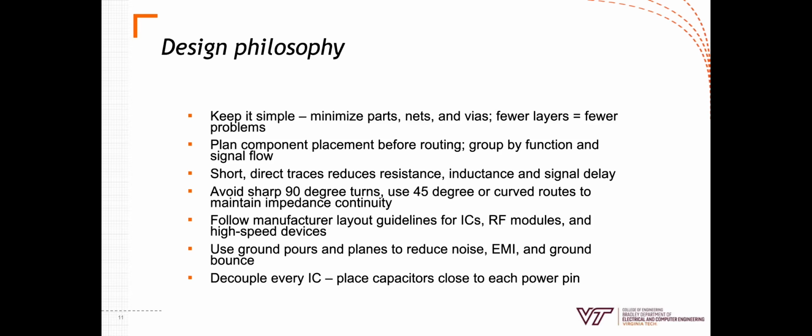If you have a small subsection for charging a LiPo battery, you're going to want to keep all the capacitors and resistors associated with that LiPo charger right next to the chip itself, and then you want to make those connections localized, and then you can take that connection and connect it to whatever subsystems need power. This makes sure that you don't have to stretch a trace across your entire board because you put the resistor all the way across.